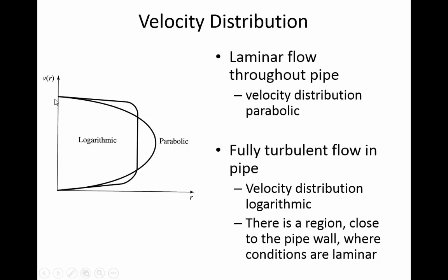And how do we know that the top of the pipe is up here? Well, it's because the velocity of the water when it's touching the pipe is 0. It has the same velocity as the pipe itself because it's a viscid fluid, meaning a fluid that has viscosity can't slip over another surface with there being no friction.